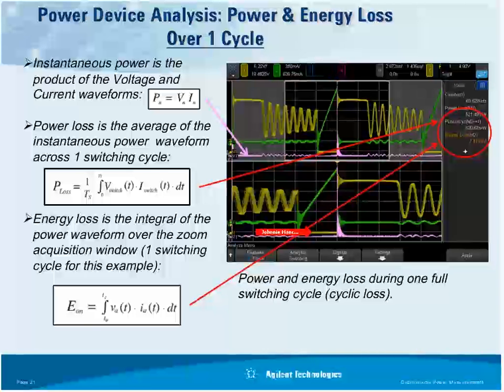All scopes have a certain amount of what you might call offset accuracy. In the old analog days, we called it balance accuracy. So when you put a waveform trace across the screen, maybe it's 0 volts, you might see a 1/10 of a division or a 20th of a division of offset.